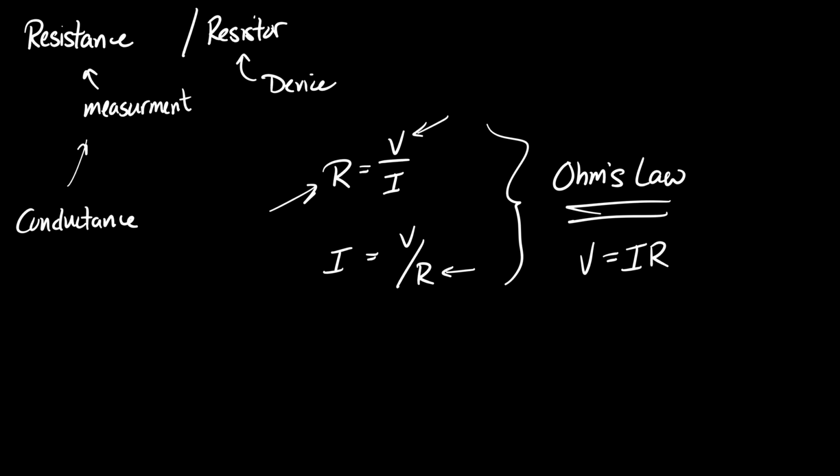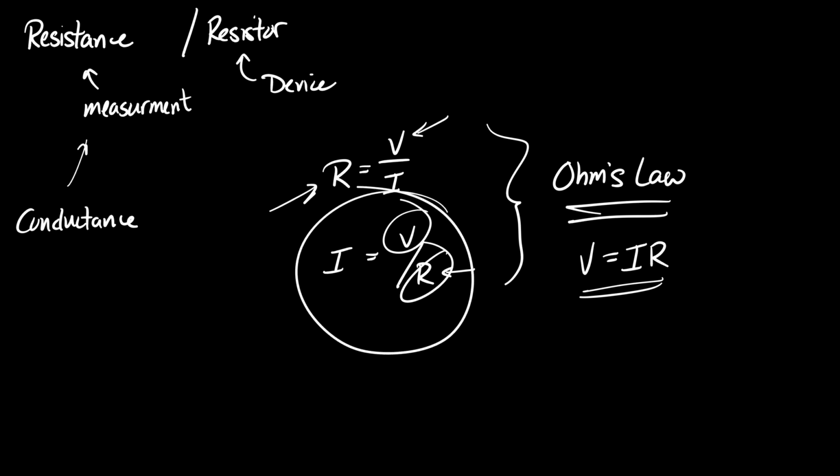Somewhat ridiculous because it doesn't show true dependence. Voltage does not depend on current and resistance. Again, voltage is established separately. You can build a battery and have no current. You can build a resistor and have no current, but current is created when you place a resistance across a potential difference. So I want to be very clear, although this is called Ohm's law, it does not have the proper dependence. The proper dependence is this one: current depends on voltage and resistance.